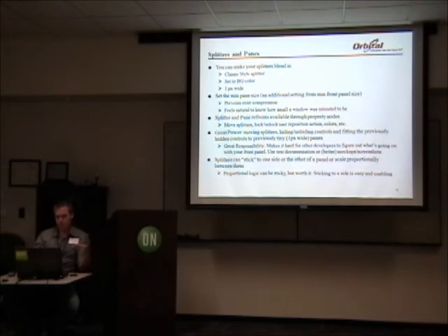Whenever you use splitters and hidden controls, like I just described, have some documentation. Take a picture of it with the splitters all highlighted in different colors and say, here are the different pieces in the different panels of my VI, for the guy that's following behind me, because otherwise it's really confusing when the main tab control disappears. Where did it go? Oh, it's in the third pane over.